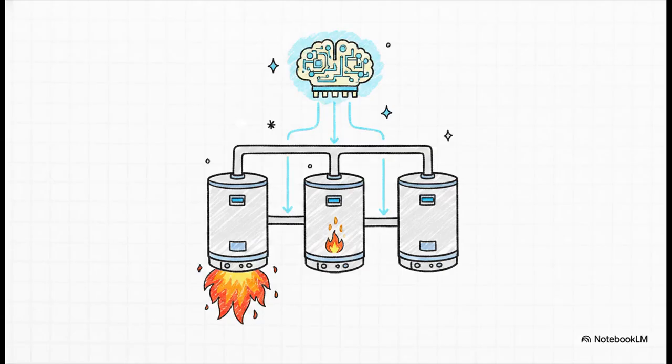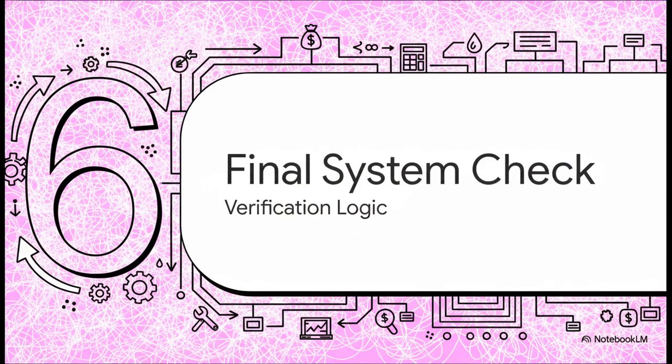Different technologies require entirely different interpretations of your math. And it goes even deeper than that. If you're looking at boiler and indirect systems, you have to confirm heat exchanger capacity and boiler recovery. But the real game changer here, especially for facilities with highly variable demands, is using parallel staged units with smart controls. Staging multiple units smartly is for sure the absolute best way to improve reliability and completely prevent the massive inefficiencies of oversizing.